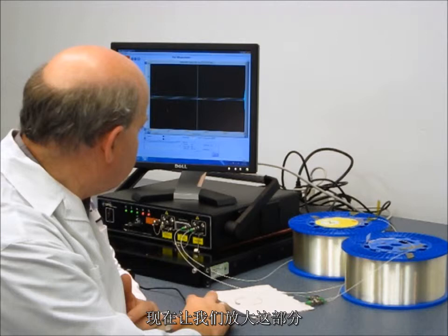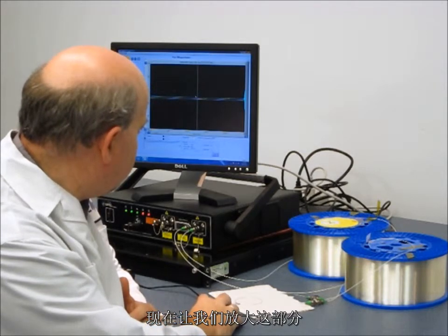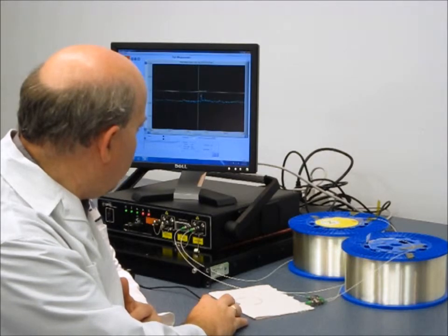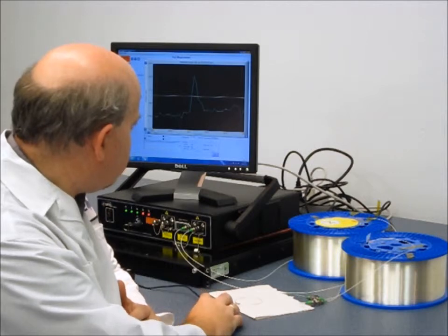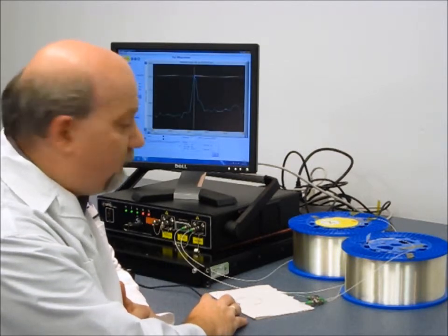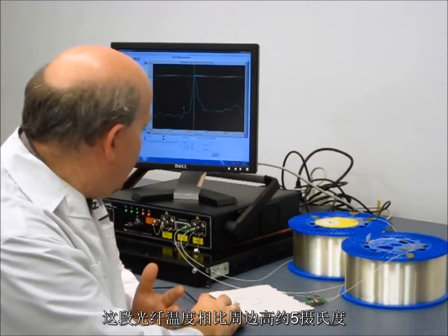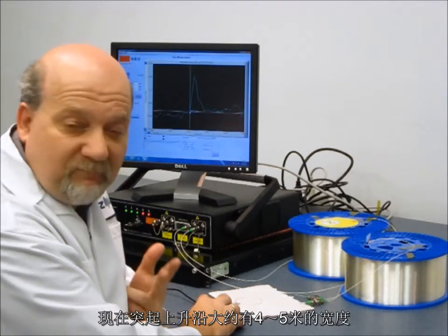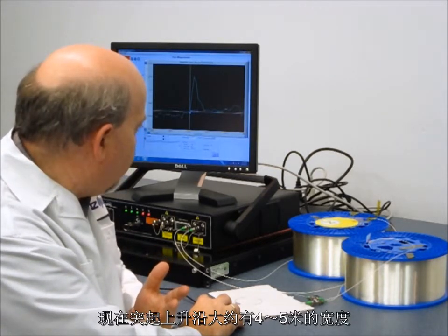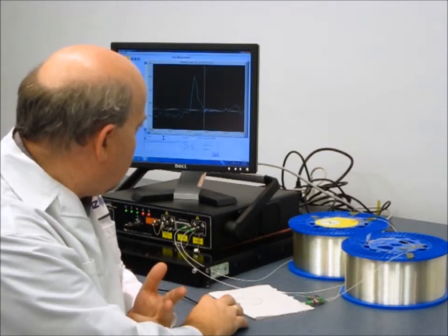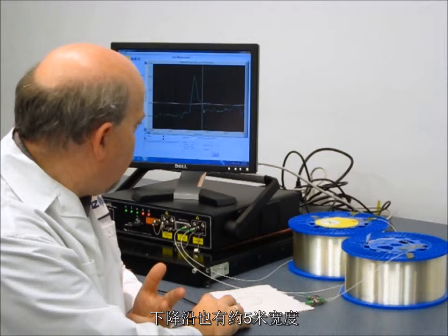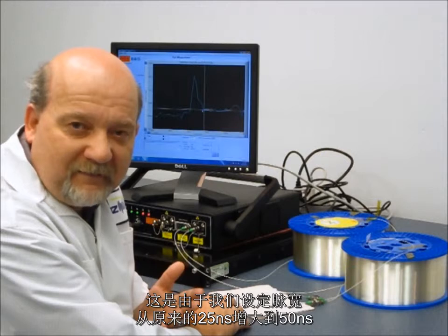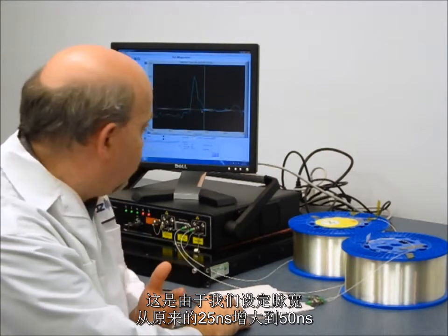And if we zoom in to this area in question, again, we can see a spike. The peak is about 5 degrees again above the background. And now it's about 4 or 5 meters below on one side for the peak. And again on the other side it's about 5 meters because we lowered our resolution by going to a 50 nanosecond pulse instead of a 25 nanosecond pulse.